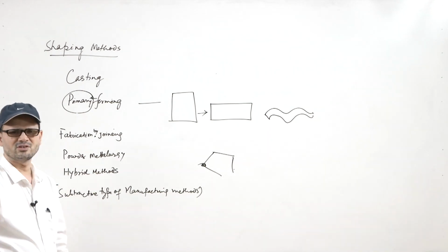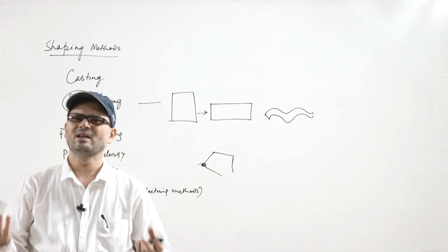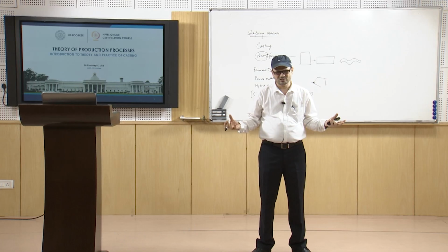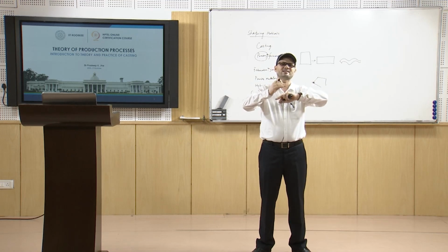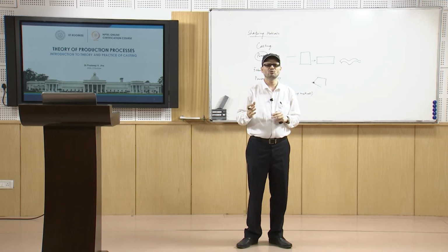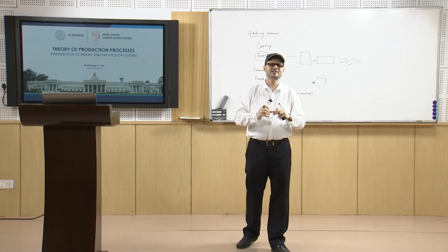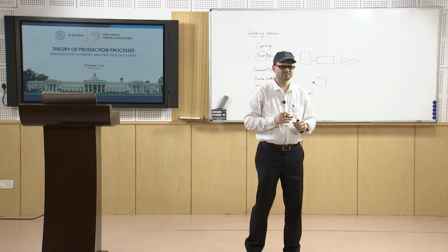Similarly, in powder metallurgy you have different stages. You will have first of all the powders of different materials, you have to blend them, then you have to mix and properly see that mixing is proper, and porosity is removed. Further, compaction is there, heating, sintering, all that. So, there are many stages, and then you get the product.